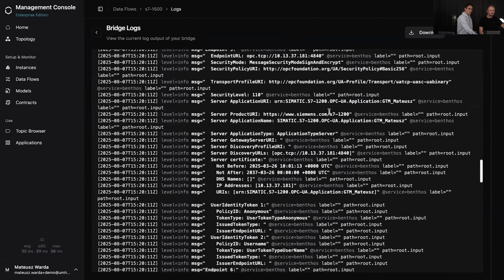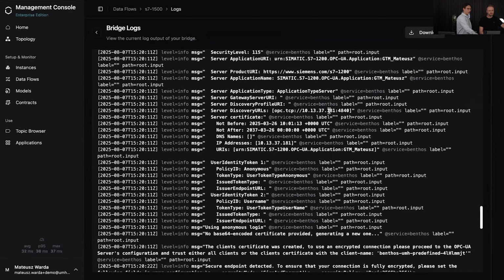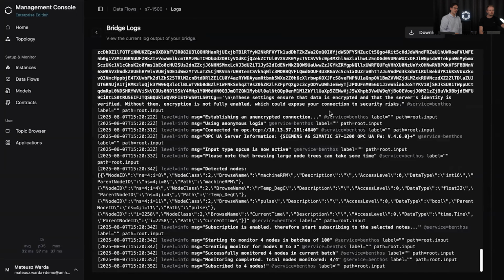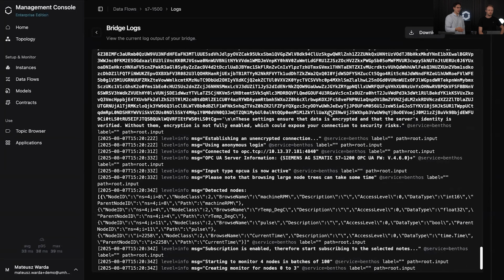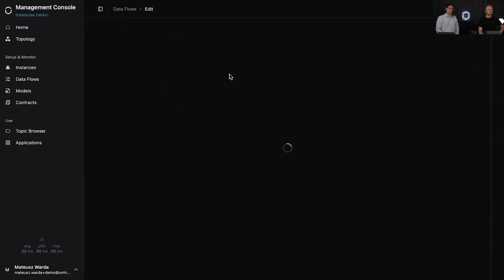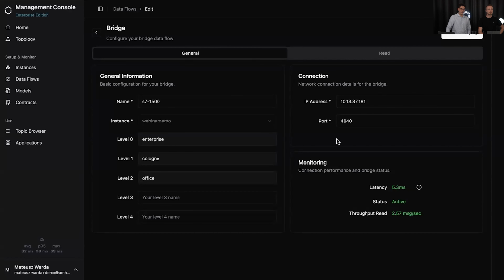So it's still completely available with all the logs that you would know and love from the UMH Classic. So even in this containerized environment, we provide multiple levels of logs for each individual bridge, for the agent running inside, etc. So no features lost on that level. Exactly. That's the same with metrics and so on, if you're interested how many messages are pushing, how many are successfully processed, which is also available via Prometheus now.